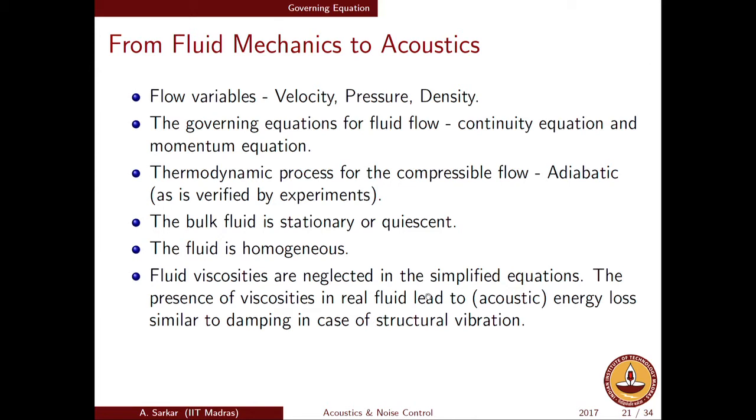Another very crucial assumption we will make for now is that the fluid viscosities are neglected in the development that we will do today, which is the acoustic wave equation. The reason fluid viscosities will be neglected is because the effect of fluid viscosity can be shown to be equivalent to an energy loss. That is pretty easy to understand, because viscosity is an energy dissipation mechanism. The inclusion of fluid viscosity, which is truly there, is going to induce some additional losses into the acoustic wave propagation, because of which the wave will decay as it travels further distances, but this decaying aspect will be ignored.